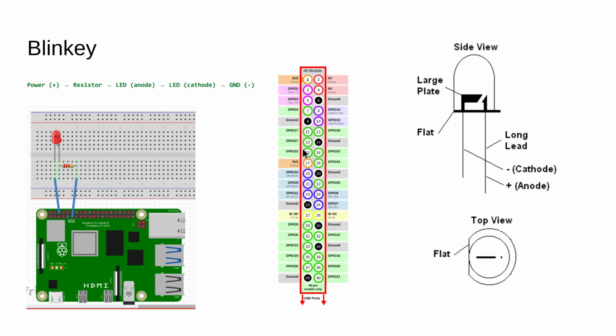So this is a map of our GPIO pins. It tells you what numbers they have on. It tells you also what they do. But we can program these pins to do things. So what we're going to do now is set up our Raspberry Pi with our breadboard with a little 220 ohm resistor, making sure our resistor goes across. If we do it in line, it doesn't fully resist because the copper wire still goes up. You can actually see where the electric is conducted on that because it lights up green when you do it in Fritzing.